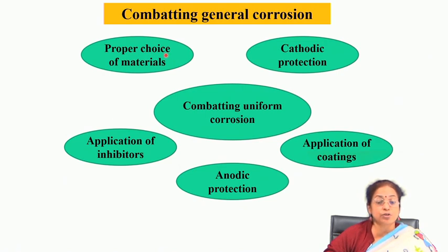On the other hand, if you use 304 stainless steel in a chloride containing solution, there will be different types of corrosion, but if you choose the proper material in the proper place, for example titanium based alloys in chloride containing solution, it will work perfectly. So, proper combination of materials is very important, so that you can minimize the probability of corrosion. Another way of minimizing the probability of corrosion is by application of inhibitors, which actually controls the environment. You can use different types, cathodic inhibitors, anodic inhibitors; all those things will be discussed again in a little more detail.